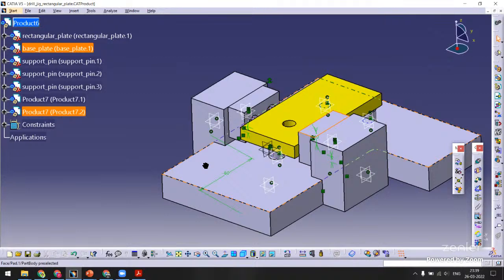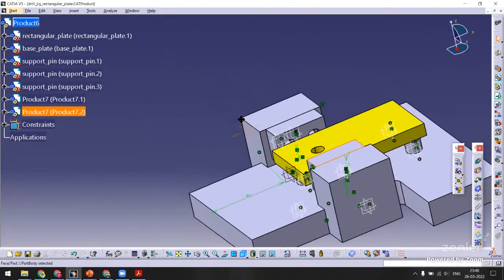But a lot of companies also use it, but I generally recommend to use a brush, not pneumatic air, so that you have control on the burrs. We don't want burrs to fall where it is not intended. We also have to protect the machine because machines are quite costly. If we can't protect the machine, we might generate loss for the company. And mind you, the mechanical engineers are responsible for saving money and making profit for the companies.